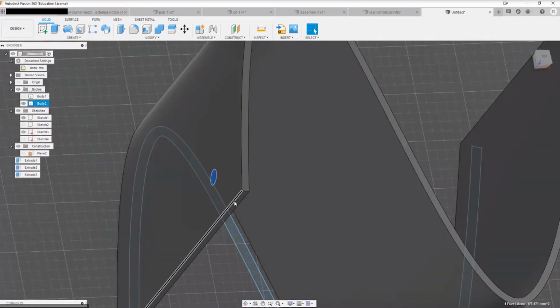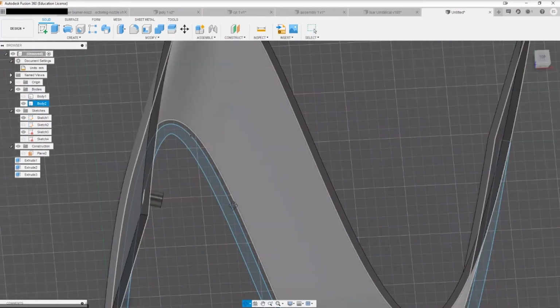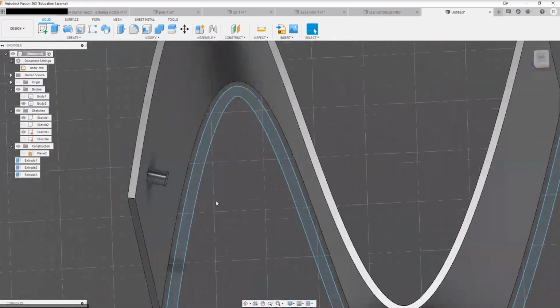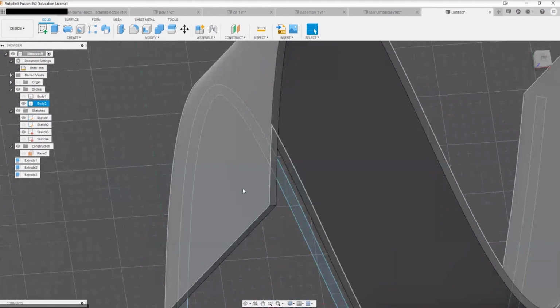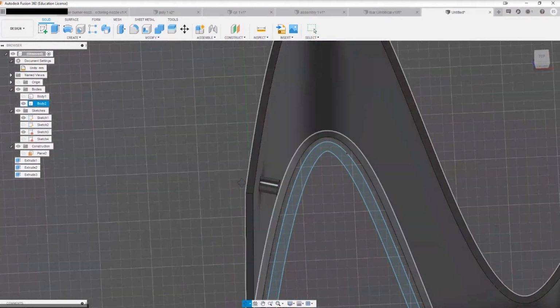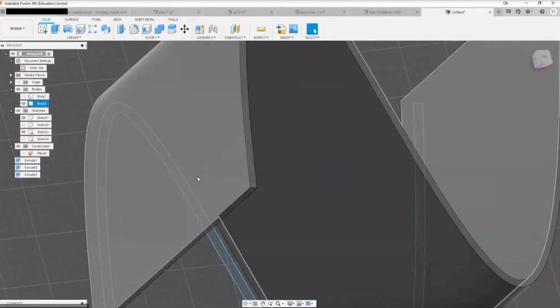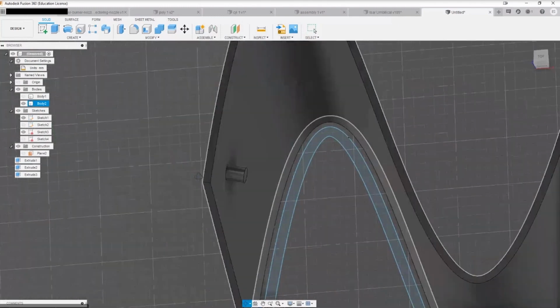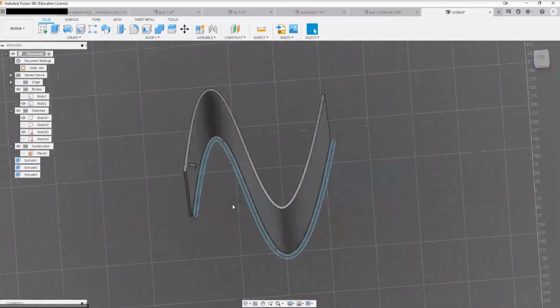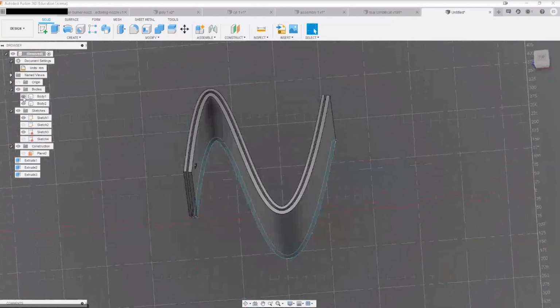You can simply just delete that, and it'll remain there. It's not going to change anything. But this is a certain kind of artifact that you need to look out for when we're working with solid bodies, and you know that you've completely smoothed out this area. You've got that face there, you need to remove it. It's just another consideration for neating up your designs.